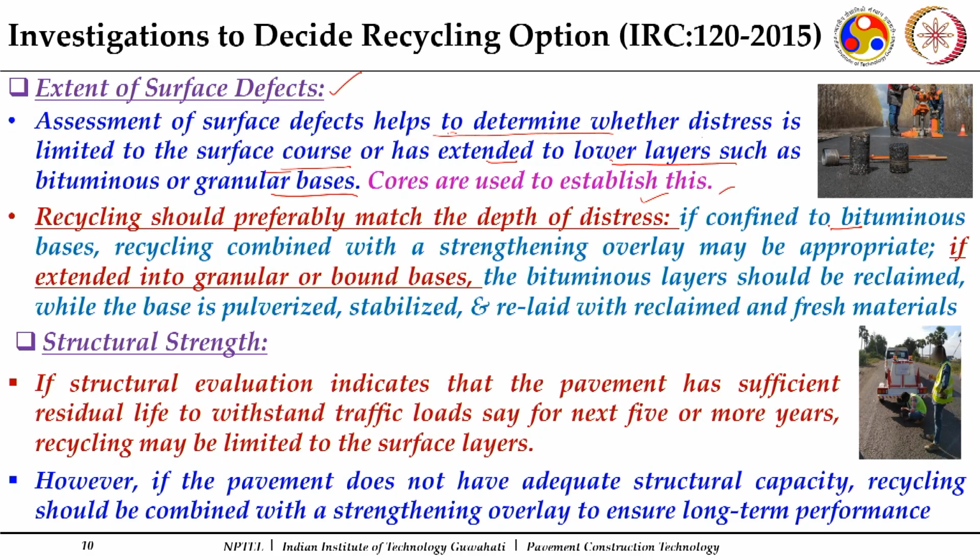So if the distress is confined to the bituminous layers, with no significant distresses in the underlying course, then we can go for recycling combined with a strengthening overlay. If the surface layer has shown extensive signs of distress, it can be recycled, and along with it an additional overlay may be provided over it.